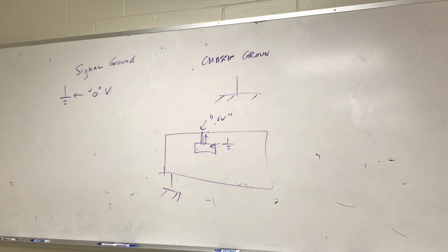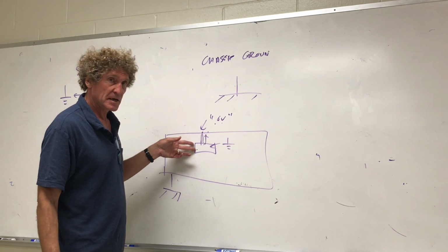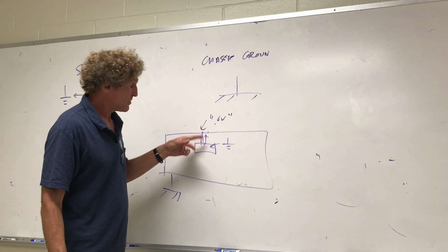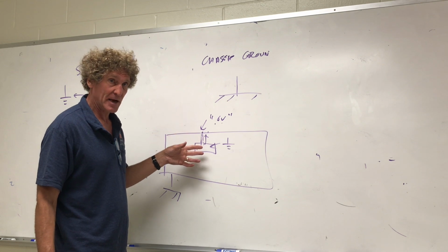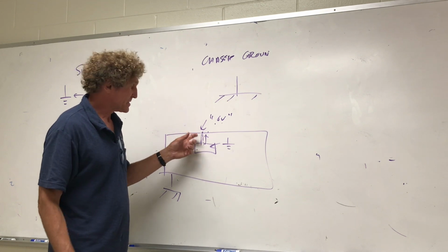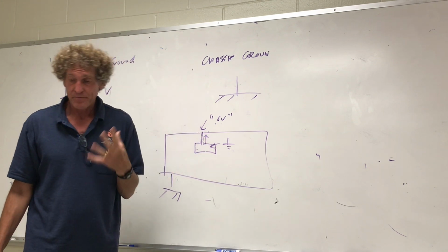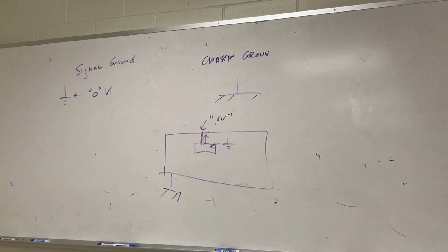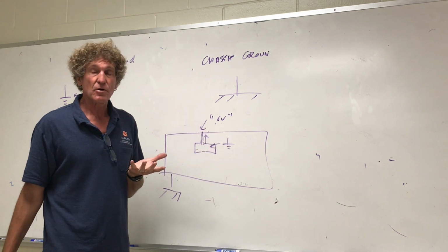The problem with that is when you're doing measurements or you're trying to do amplification of an incoming signal from an antenna, and it's got a very small signal you're trying to amplify. This right here may have such a significance that if you're feeding the antenna's input into this, that difference right there will cause, remember, anytime you have a voltage potential, you have a capacitance, right? Anytime you have a capacitance, there is going to be mutual inductance and mutual capacitance between these 2 points. And if you've got a high frequency oscillator on there at 2 gigahertz, that 2 gigahertz, wherever it might be, might bleed into that, and it'll cause the problem.